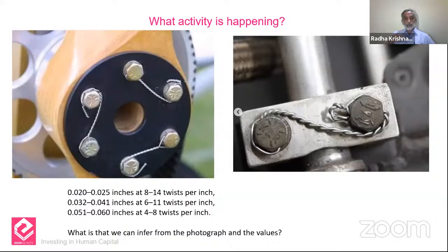basically, it is an approach of an aircraft for landing. And the approach of the aircraft for landing has to be clearly visualized. If it is a visual flight range, the pilot is expected to see the runway in the most critical way and take the right decisions at the right time. This instrumentation is called PAPI, P-A-P-I, Precision Approach Path Indicator. Now, if he does not follow the Precision Approach Path Indicator, what happens? He might create a Calicut incident.